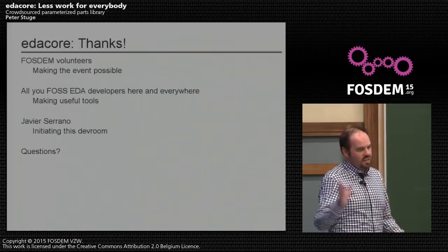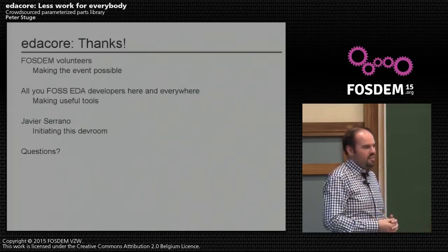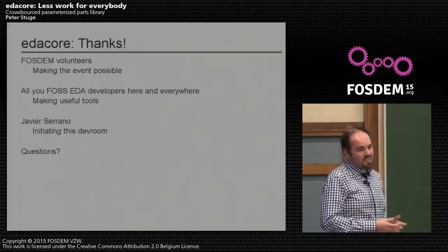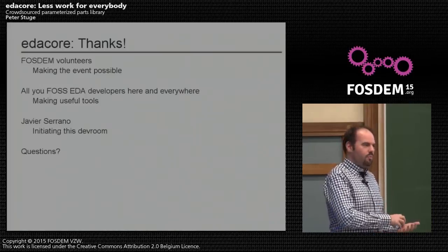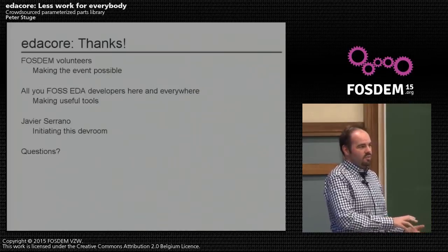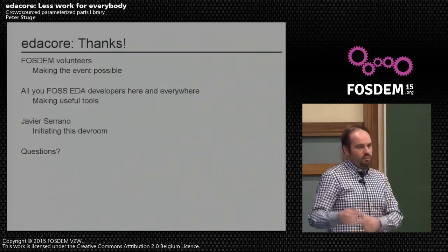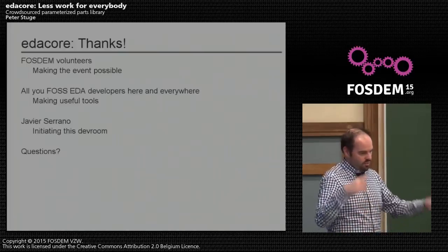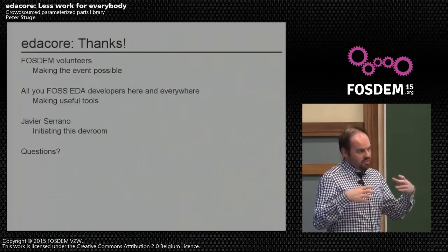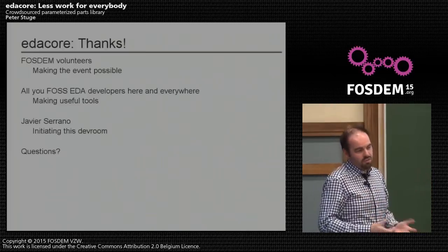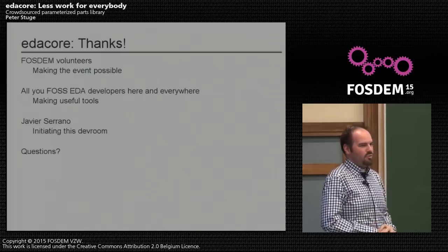At the moment it's just a flat namespace of lots of different parts. Baby steps: associating different footprints with one particular part so that at least the symbol stays the same, or there are 2 variations of the symbol and 4 variations of the footprint, and I can choose which combinations I like, but it's still the same logical part. That is something I'm looking for.